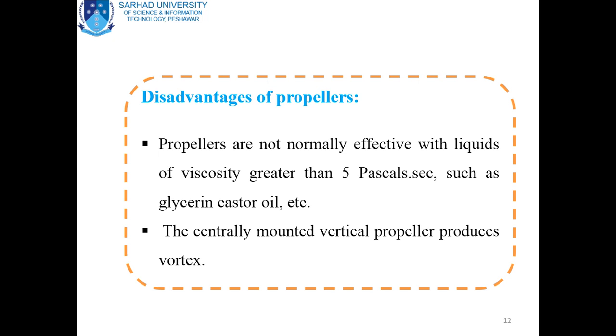Because of the greater viscosity, that is more than 5 Pascal second, propellers are not effectively used. It is one of the disadvantages of the use of propellers for mixing.